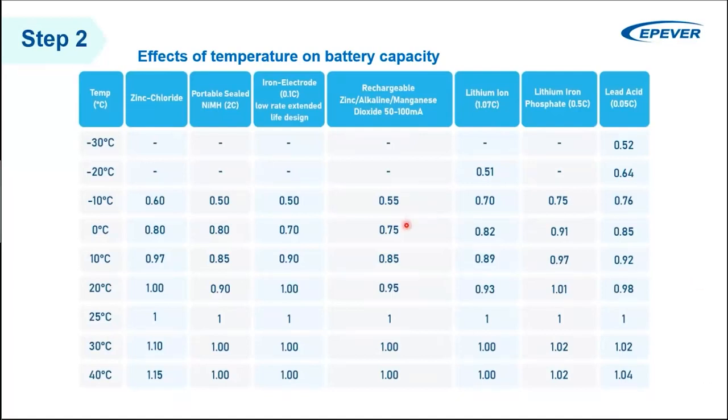About the temperature, you see here a table. Here you see the temperature, and here you see the different types of batteries normally used in the market. When the temperature increases, this affects the chemical reactions that occur inside a battery. As the temperature of the battery increases, the chemical reactions inside also quicken. At higher temperatures, one of the effects on lithium batteries, for example, is greater performance and increased storage capacity. Scientific studies claim that an increase in temperature can lead to up to a 20% increase in the maximum storage. However, there is a side effect to this.